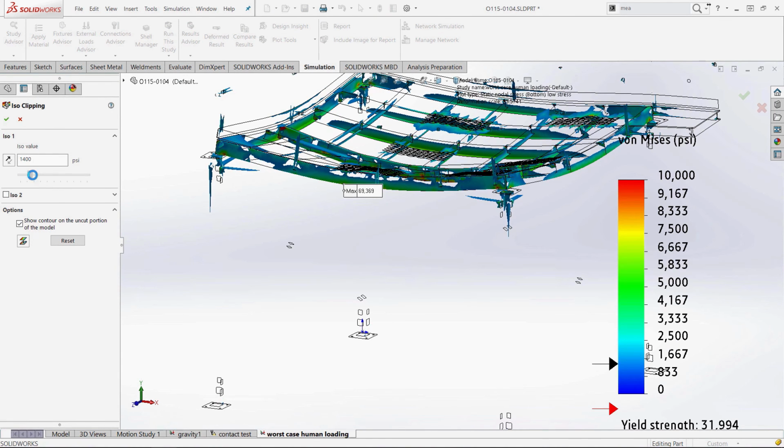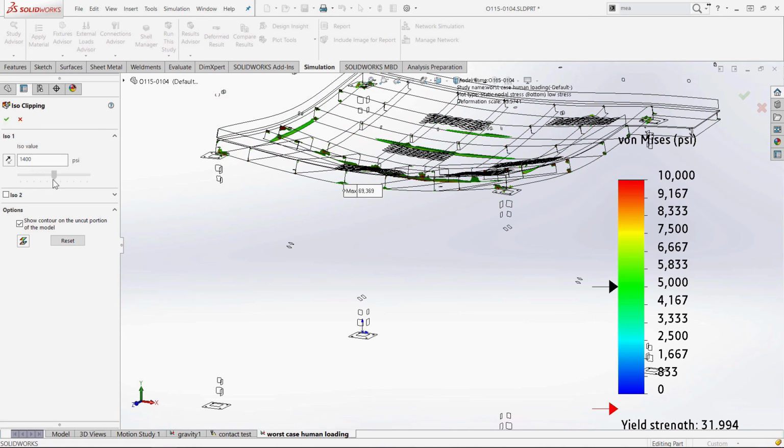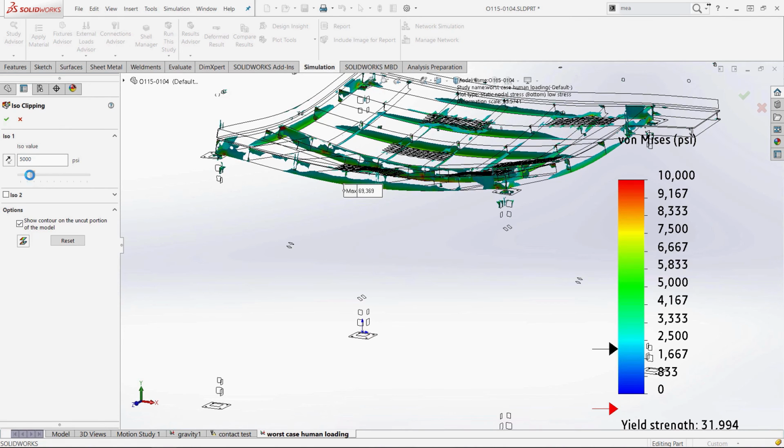I really need to see where the critical stress is and bending in some of these floor supports, as well as where the critical joints are, as well as actually taking some fastening features like welds and fasteners into account. So we're going to set this up from scratch from the SOLIDWORKS solid geometry and get into these results by the end of this episode.